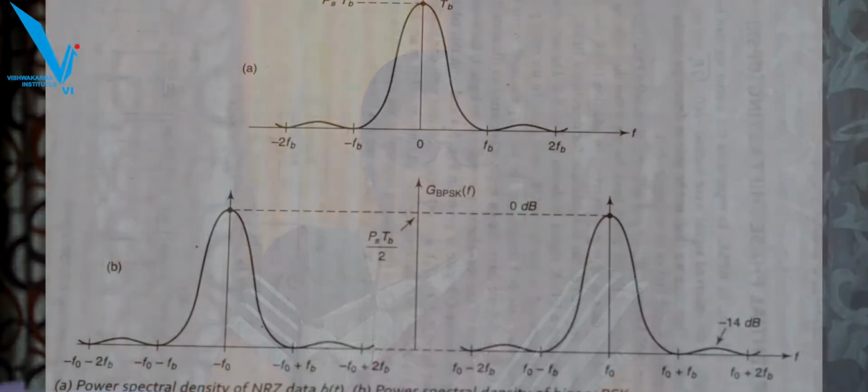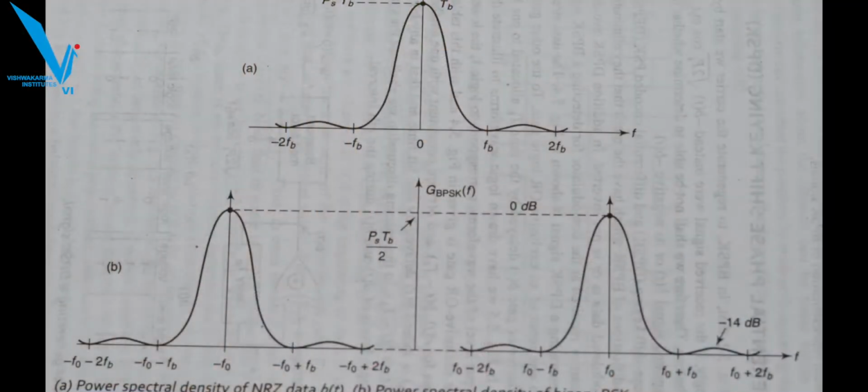So now we have seen how the blocks operate, what the output is, and how the demodulation, carrier recovery and bit recovery is done at the output of the demodulator. So this represents the PSD of a BPSK signal.